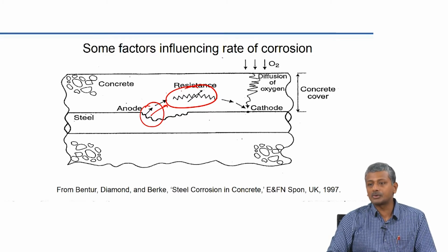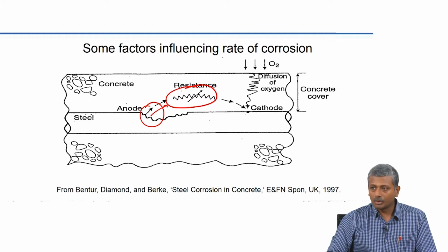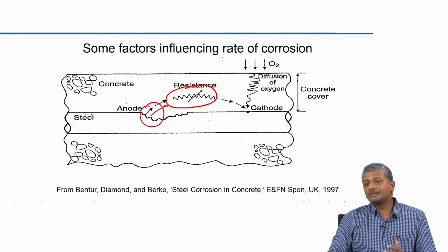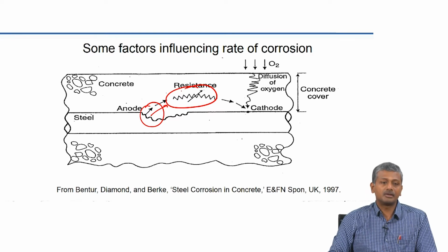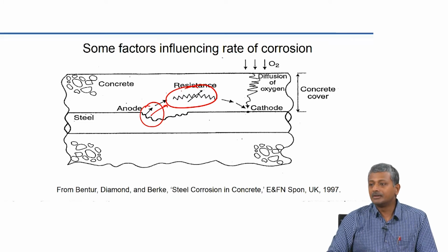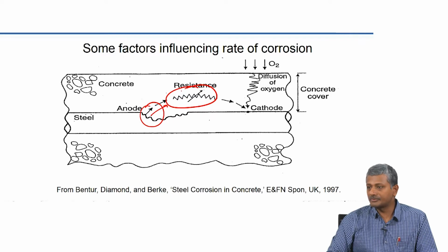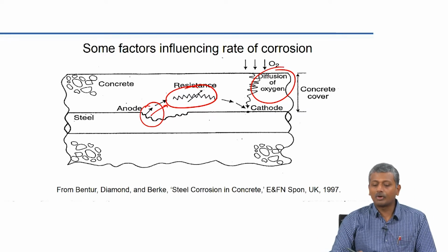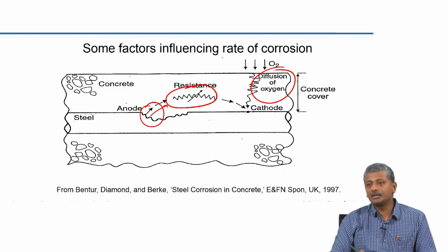So, in a chloride induced corrosion environment, you might actually get a very positive response when you use mineral admixtures as replacement for cement. In a carbonation environment, as we discussed earlier, you have greater porosity after carbonation in the systems with supplementary cementing materials. So, you may actually end up causing a lot of these pores to get interconnected when the carbonation process happens. But the other factor, that is the availability of oxygen and moisture, may still be restricted in a system with supplementary cementing materials.